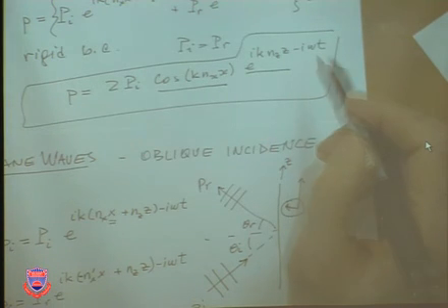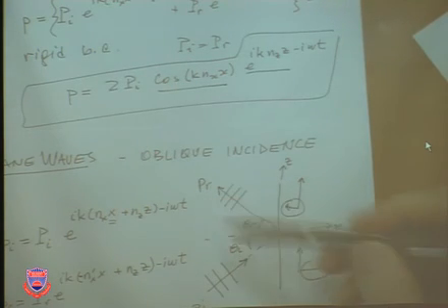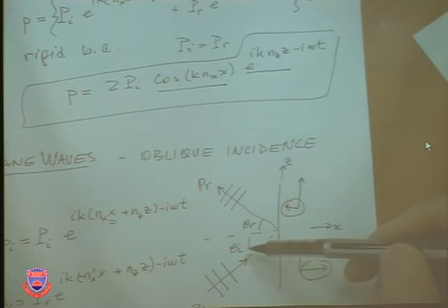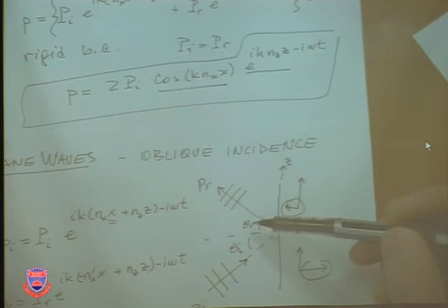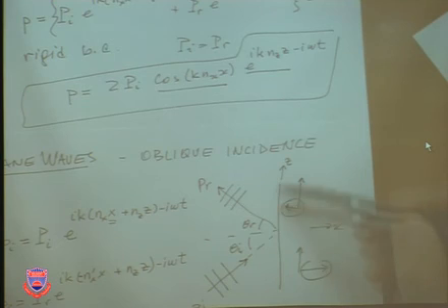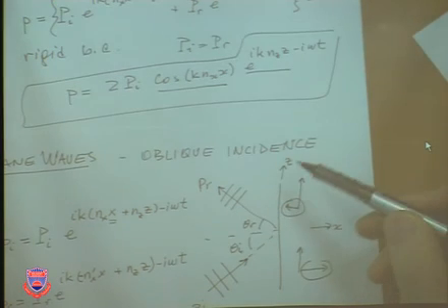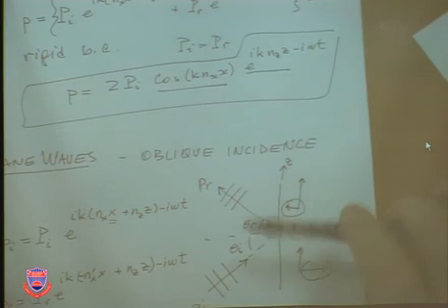There's no reflection in the z direction. And how did we obtain all of this? By simply writing the equations as if we do not know what the amplitudes are, which we don't, or the relationship between them. We just wrote, in general terms, incident and reflected pressures and angles, but we did know the boundary condition. The key here that you need to remember is the boundary condition was particle velocity is 0, but only normal.